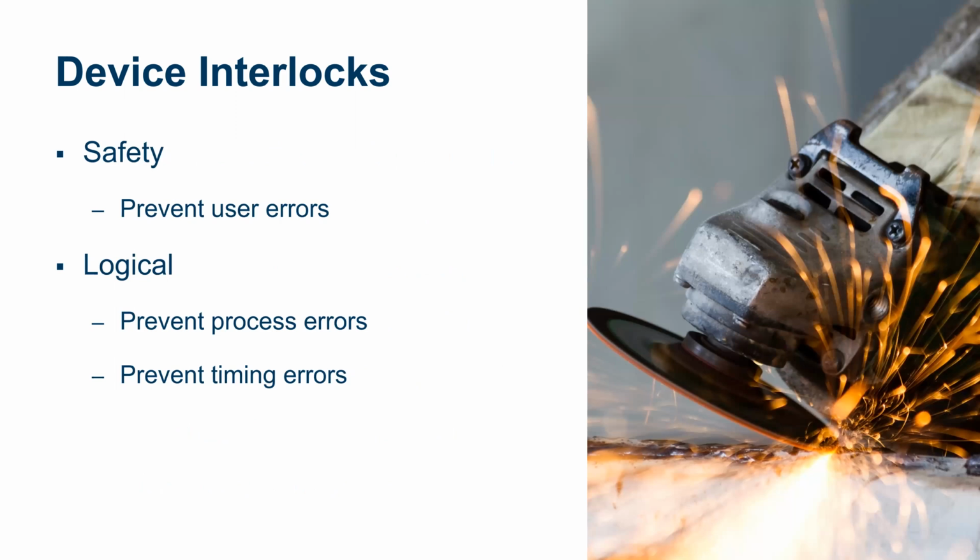Okay, so interlocks, right? They're primarily there for safety in power systems, but in processes you often have other reasons to put an interlock in. If you have a complicated process with a lot of inputs and outputs, you'll put that logic into an interlock to make sure the output can only take the correct choice. So you write your logical equations based on your inputs and outputs, and everything should just work as long as your engineers have correctly devised your system. Also, timing will come into this a lot of times, so you'll have some logic based on when you get the commands.